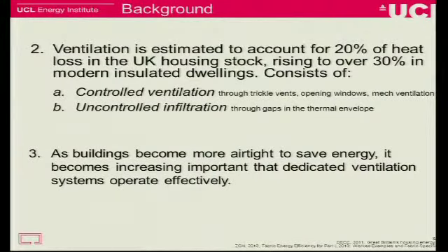So in order to save energy, the mantra has been for quite a while to seal tight and ventilate right, you may have heard. And the idea for that is to remove the continuous background infiltration and bring it all into the realm of occupant control. But the risk we run with that is that if these systems that we have to ventilate, if they don't operate as anticipated, then we run the risk of causing problems in terms of occupant health and comfort.